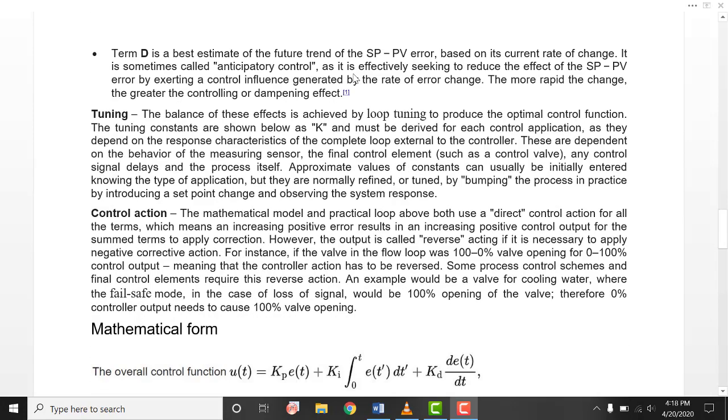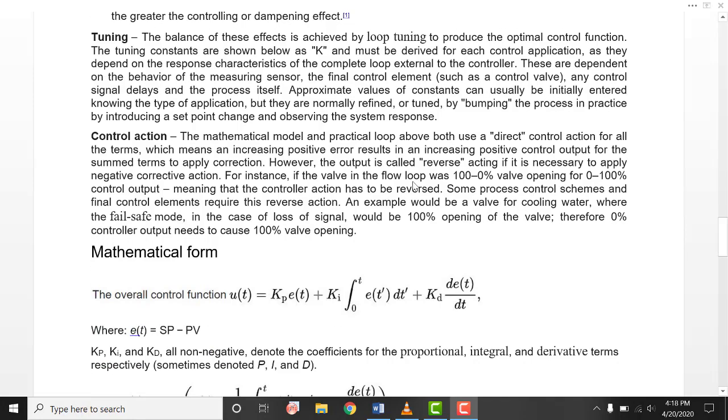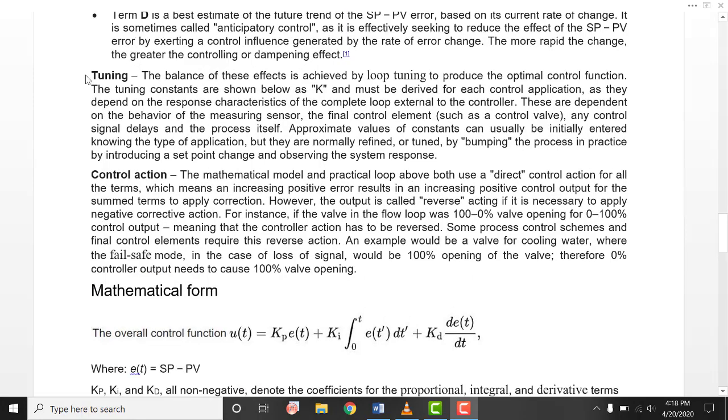Okay, so I have also created a short video lecture which will help you easily understand what these things are and how you can understand this. Now this is tuning. Tuning means controlling how this complete loop system is controlling your main output, such as control of the valve from 60 to 70% or 80 to 90%, or controlling of the thermostat at the output to achieve our required temperature using this PID control.